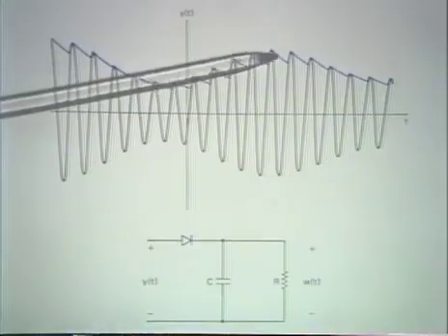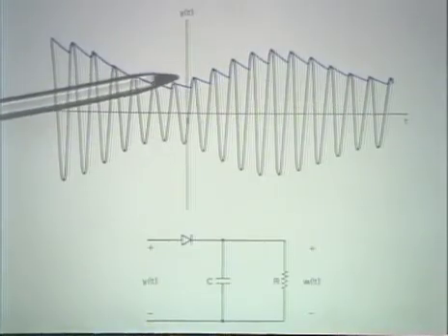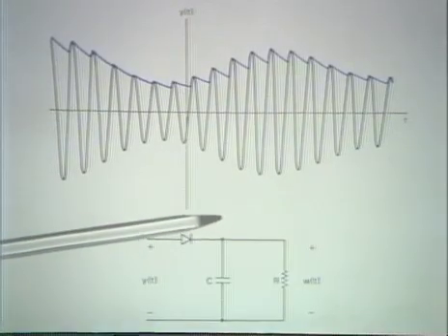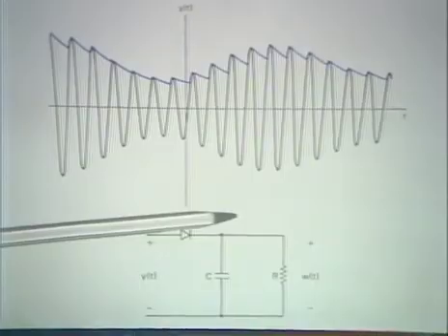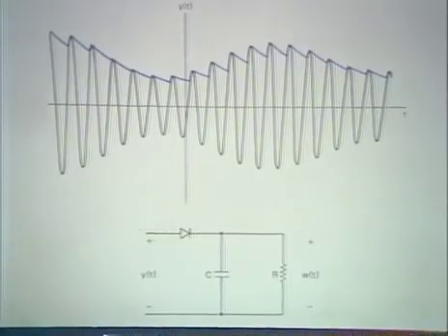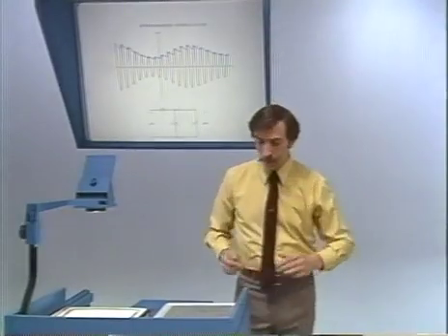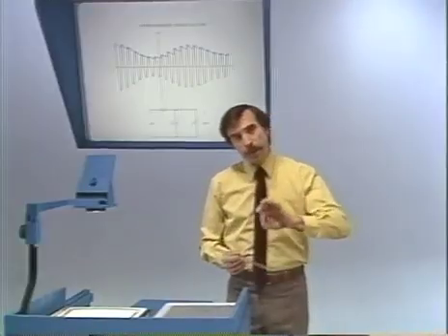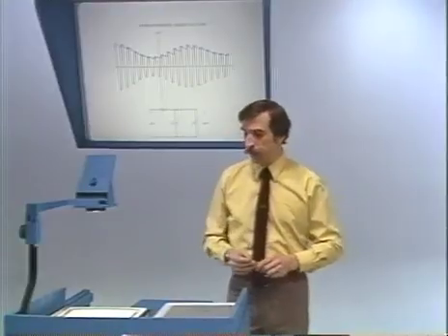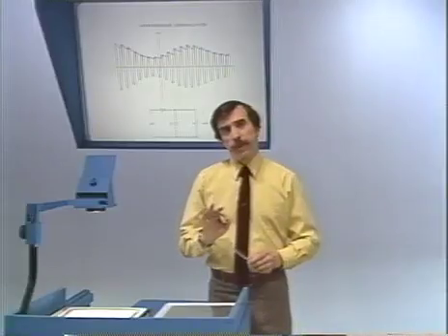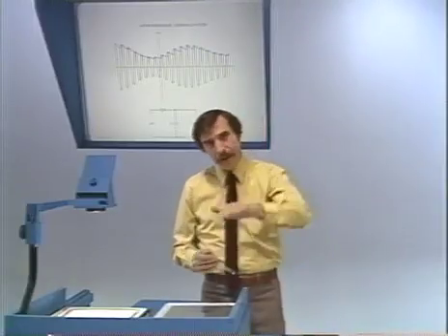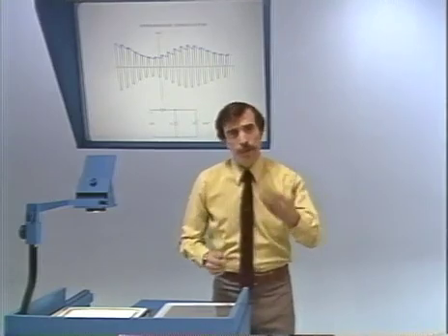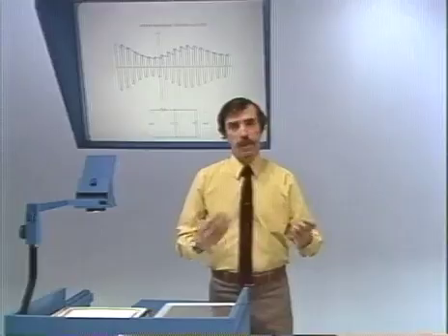It's a demodulation that doesn't require synchronization between the modulator and demodulator. And it's fairly inexpensive to build, but it has obviously some trade-offs associated with it. Well, to indicate where the trade-off comes from or where the issue surfaces, notice that what we're doing is tracking the envelope of this sinusoidal signal. And we're assuming that that is our original signal x of t.